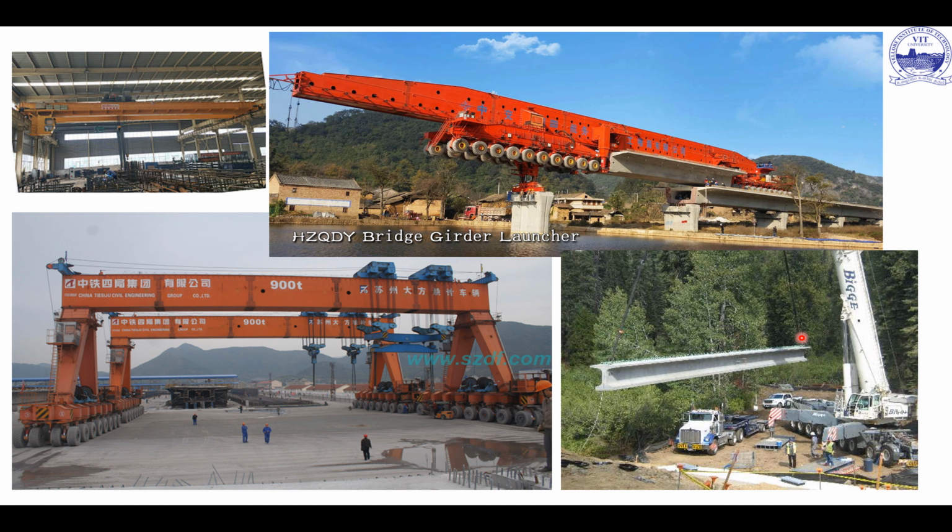Usually what happens is, one of the companies which was sharing their experience with us was telling that almost 50% of the inquiries which they get for precast construction are rejected only because the site is not amenable for precasting. The site cannot accommodate precasting work. That is, you need sufficient space for stacking and for lifting.